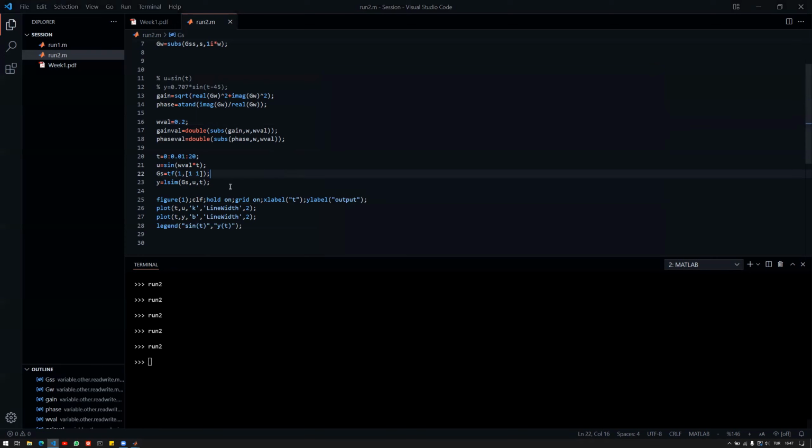Now, using this small analysis, I can conclude that this system is a low-pass system, a low-pass filter, because in the low frequencies it does not really attenuate that much, but in the high frequency ranges, it has a high attenuation. Now, how can I judge the attenuation of the system by looking at a graph?